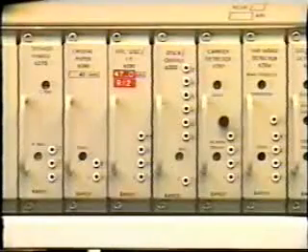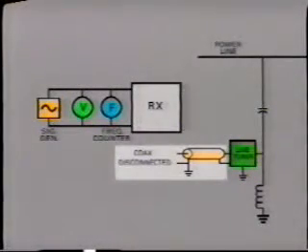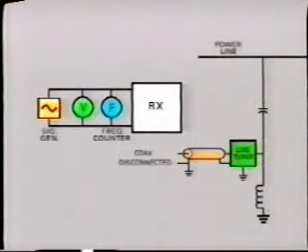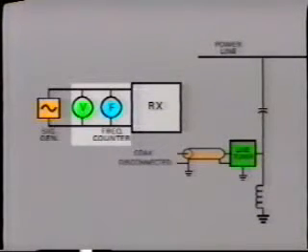Here is a typical test panel for a typical receiver. For this test, the coaxial input is disconnected, and instead a test signal of known frequency and power is fed into the receiver. The test signal is provided by a signal oscillator or signal generator. A frequency counter and RF voltmeter are also connected to monitor the signal.